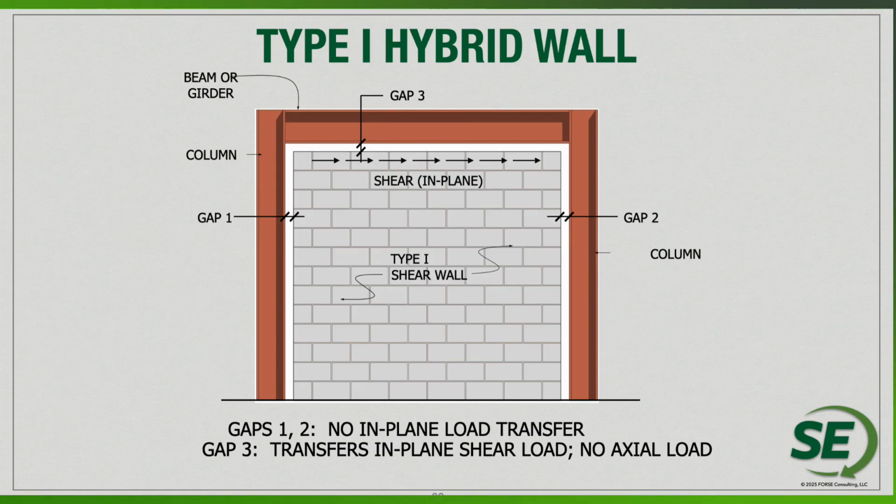But what we do is we do leave some capacity on the table, because the masonry wall does have a lot of vertical load bearing capabilities. And if you remember back a few slides, if we add in some of those vertical loads, we actually increase the overall shear wall capabilities of the masonry wall as well. So there's got to be a little bit of give and take here.